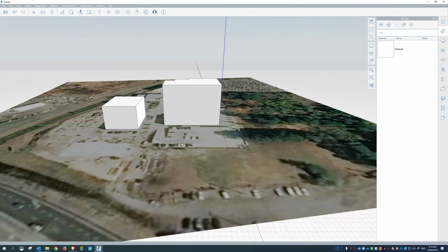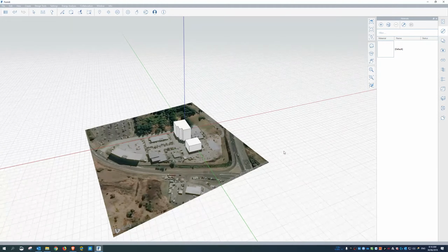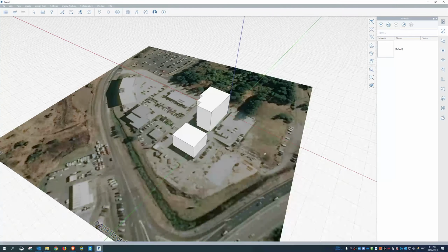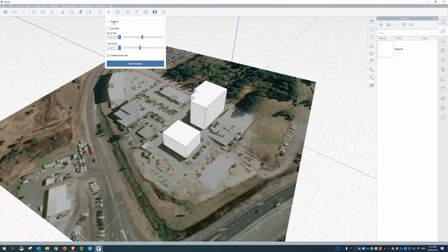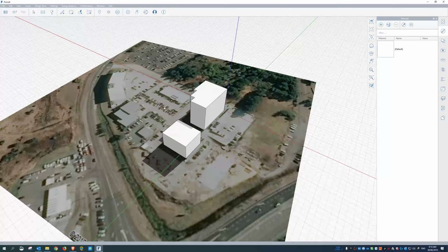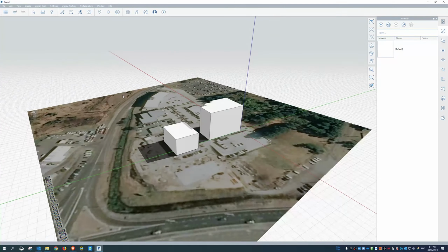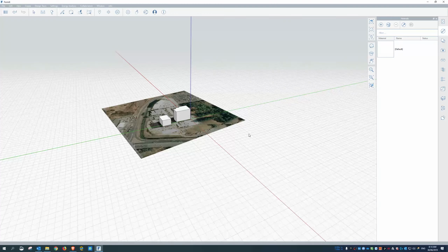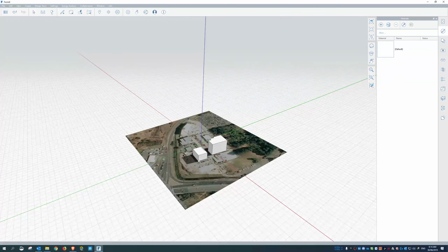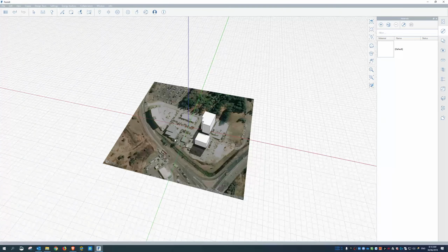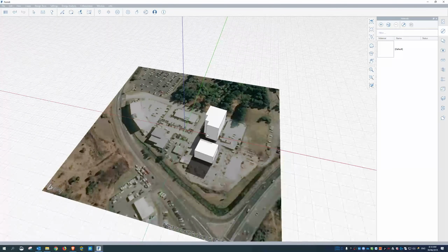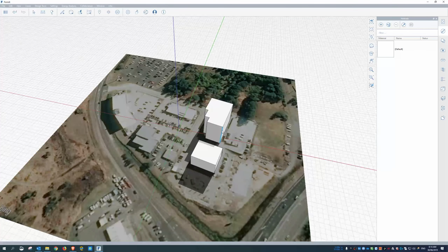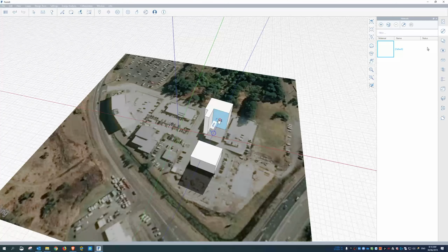Okay, and then once I'm finished doing whatever I wanted to do on that site, let's turn the shadows on just for argument's sake. So there's our two buildings that are aligned with the existing ones there. When I'm finished with whatever I'm doing, I can just right click out here and then reset the axis back again. Okay, and then let's say you're remodeling them or doing something, you can obviously just come in here and press and pull faces and do whatever you need to do.